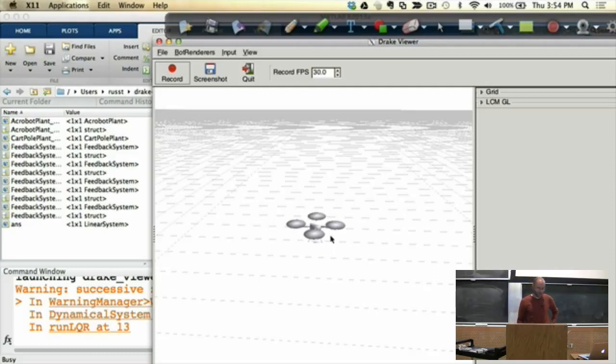Good. The last thing, which I'll put in the notes and won't bother writing out here, is that if you want to linearize a system based on the manipulator equations, the structure of the manipulator equations is very compatible with doing linearization. It's much, much easier than if you had an arbitrary f(x) grab bag. So if you find yourself with H, C, and G on a piece of paper and you want to find the linearization, it's much easier than you think. That'll be in the notes if you like.